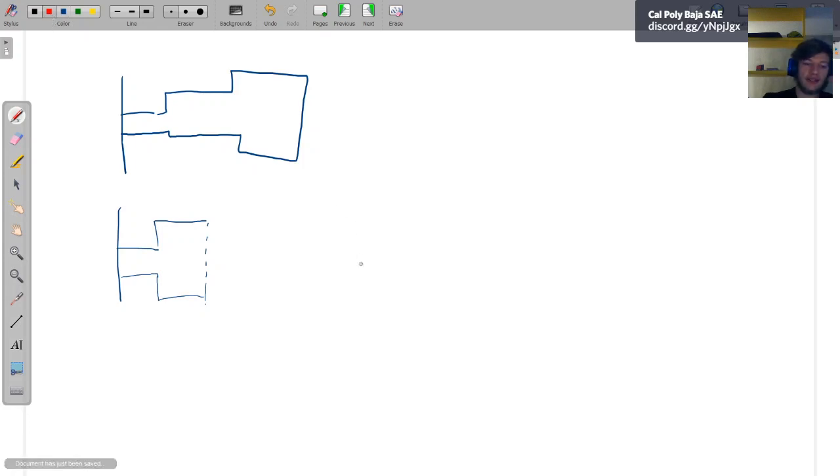In fact, when you do this by hand, there's no way you ever want to handle all these little variables. It's tedious, it's annoying. So we know that E is constant for everything. We know P is constant for everything. We know that all of these little sections are the same length, so L is constant for everything. So really, this just becomes P L over E, and technically this is L over 3.